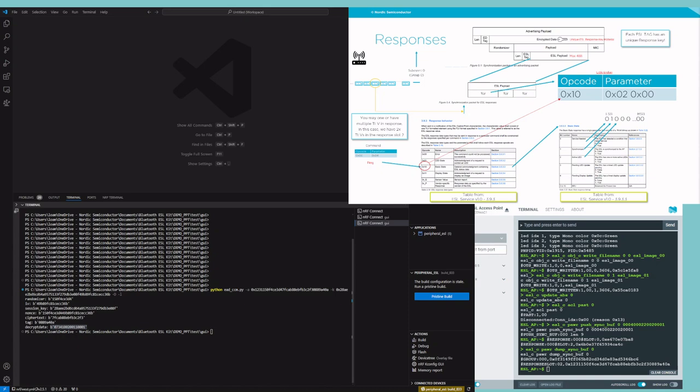As you can see, this tool returns several parameters. We will not analyze all of them, but we can go through some of them. The first 2 digits, 07, indicate how many bytes are following. 34 indicates that this is an ESL EAD, encrypted advertising payload. And then we have 2 TLVs, which are the 2 responses to the 2 TLVs that we have sent. In this case, we have sent a ping plus a command to change the image. And we can see that the first TLV that we receive here is TLV 100-200. This is exactly what we were expecting as a response for a ping, as we have seen earlier in the slides.